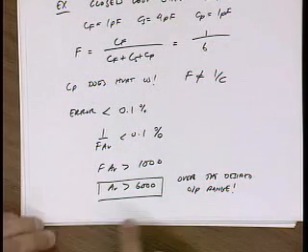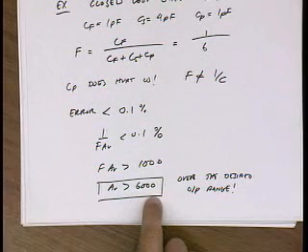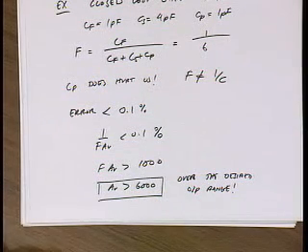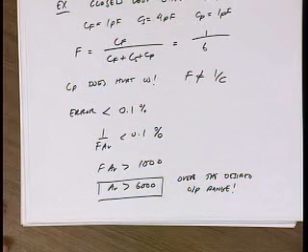You want to make sure that the gain is above 6,000 over process and temperature over a swing of 1 volt. If you do that, you're set.